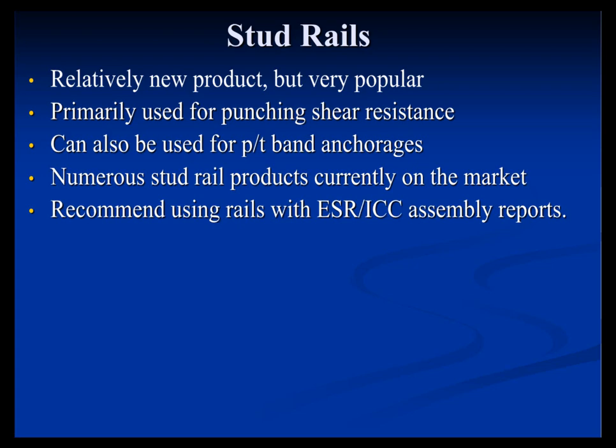So what we do now, hindsight being 2020, is that we provide the documentation or the specifications for the stud rails that we want, the minimum strength and all that kind of stuff, and then just say, but they also have to have an assembly report. And that usually ends it. Now, if you're new to stud rails or in your neck of the woods, they're just starting to use PT flat plates or rebar flat plates, whatever it is, just be wary of that. Do not allow someone just to slap studs on a rail and call it good.